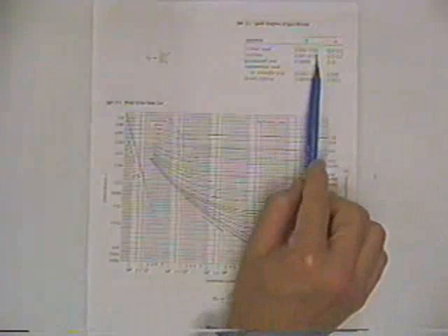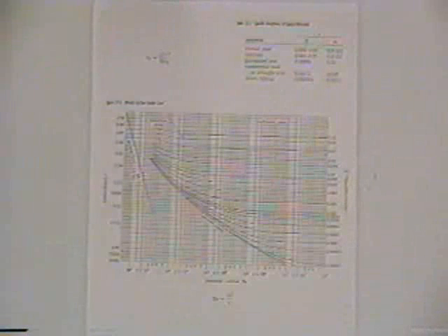And this is an absolute roughness. So if you picture a pipe, in some of the early experiments people actually glued sand grains inside the pipe so they could have a measured amount of roughness, and then they could change the roughness. So that epsilon is a representative average roughness on the inside of the pipe.